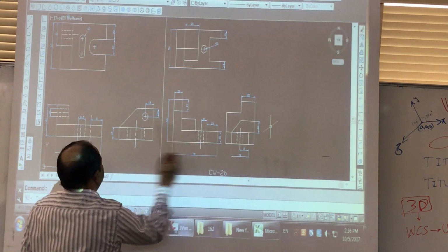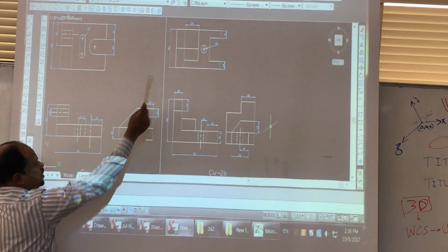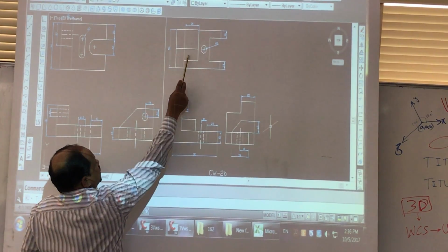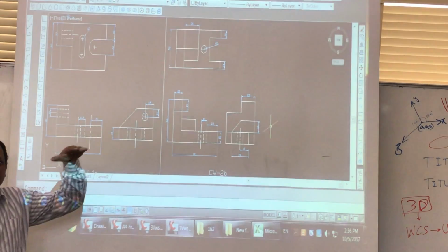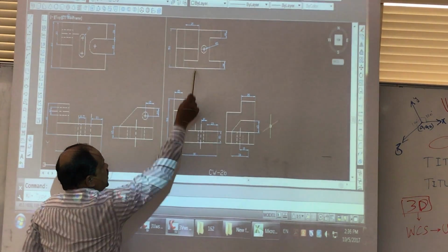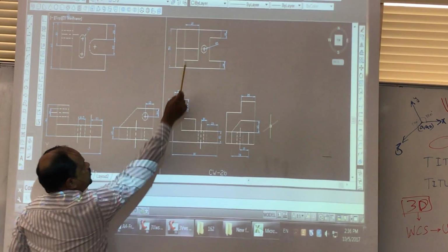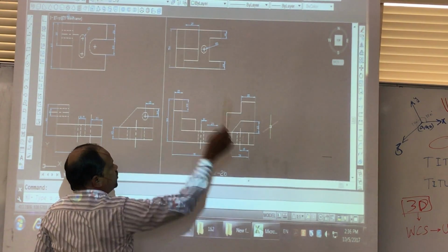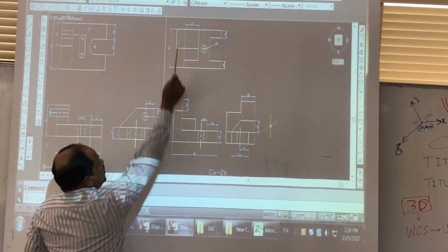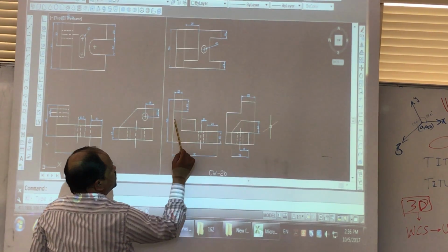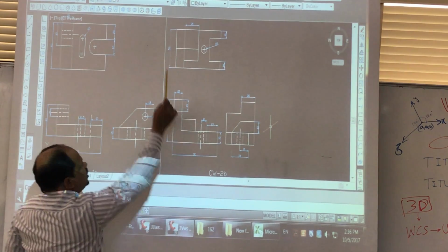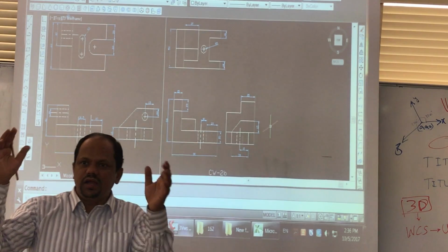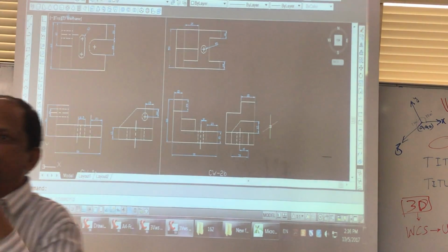What is it? The base plate is same as this. But here we have two levels. Instead of two rectangles like this, these two, I added two more rectangles. Now you have to know where they are and what is the height. Take the line, it is coming here. This is the height. It means this rectangle is here. Okay, so the first rectangle is a straight, the second what you see is an incline. What about these two rectangles? This is straight, then it goes down, the second rectangle is at this height. So each one is showing this is the height, this is the position. Okay, so you combine the front view with the side view to produce how it is.